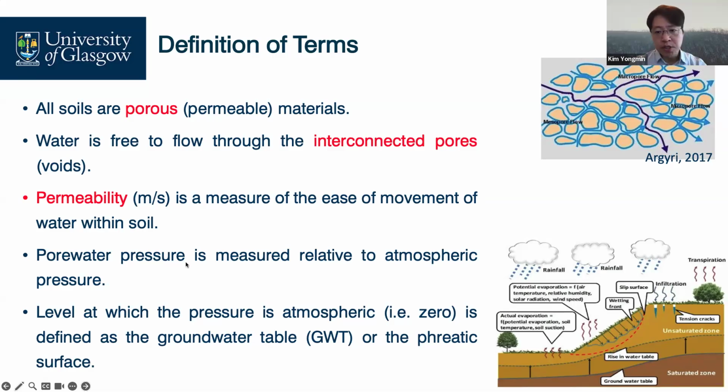And pore pressure is one of the key parameters governing the strength and stiffness of our soils. So we need to know the pore pressure under static conditions or transient conditions where pore water flow is occurring. This is known as seepage.